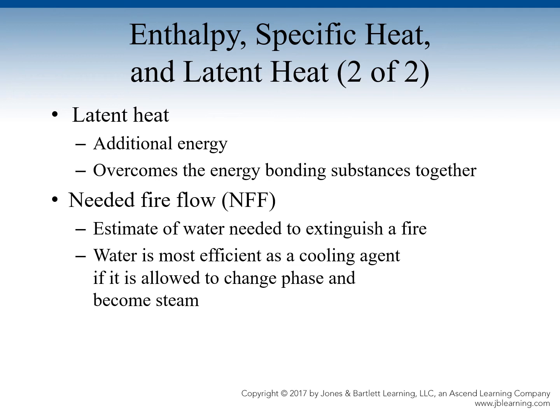Needed fire flow, often abbreviated as NFF, is the estimation of water that is needed to put out or extinguish a fire. Water is most efficient as a cooling agent if it is allowed to change phase and become steam. So we're looking for this steam conversion.